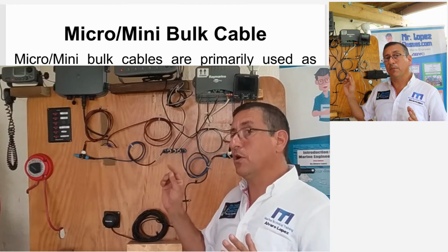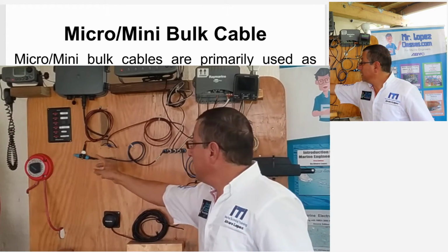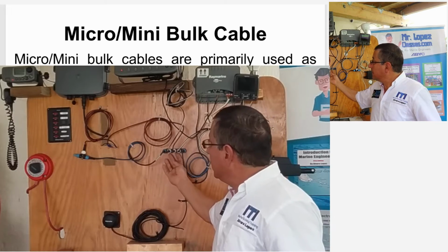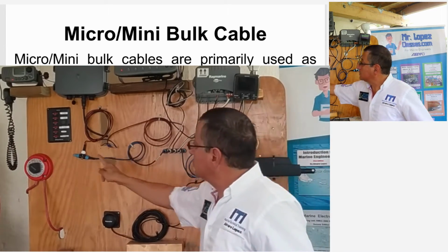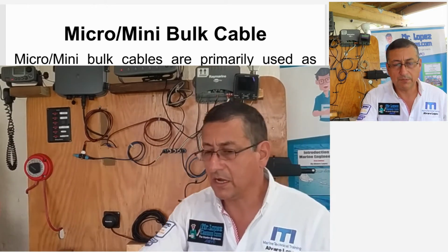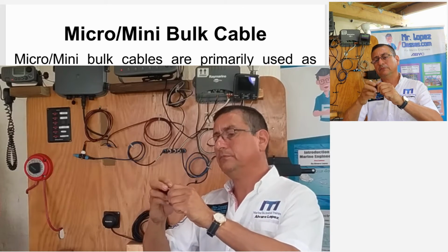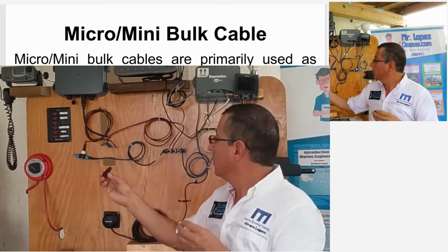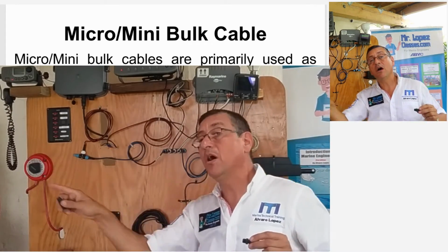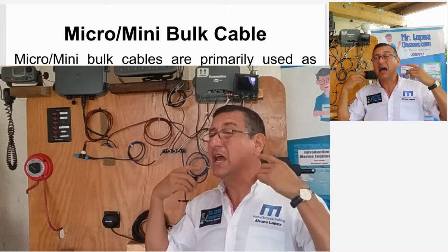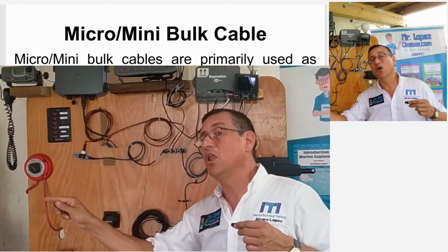In order to connect properly all of those elements in the backbone, we are going to use the appropriate cable, the appropriate terminals, and we are going to start and finish with terminal resistors. I have a couple of terminal resistors here. Terminal resistor like this. One at the beginning, other at the end, in order to close the loop of the information and avoid ringing in the loop.